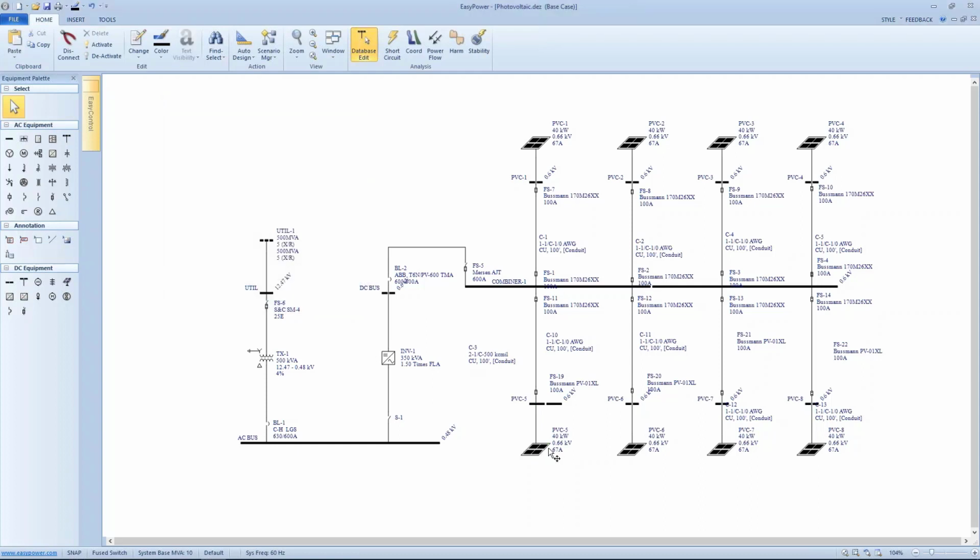We're able to cut and paste to make everything. Now, if you look at certain reference documents, there are different philosophies on where fuses need to be placed in the system. In this particular case, we're using an array. Some people would prefer to fuse strings.